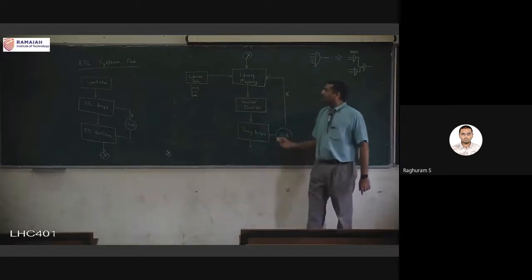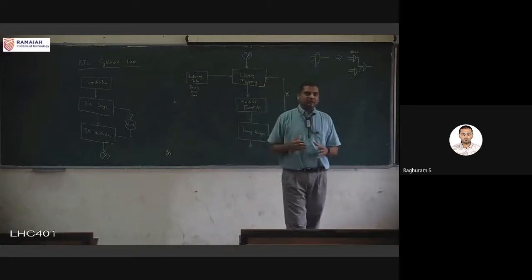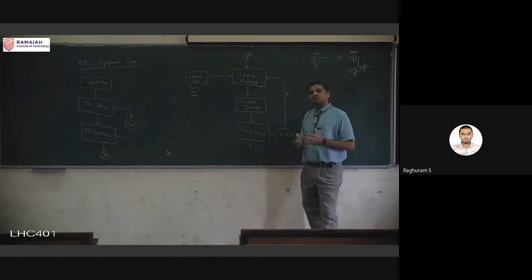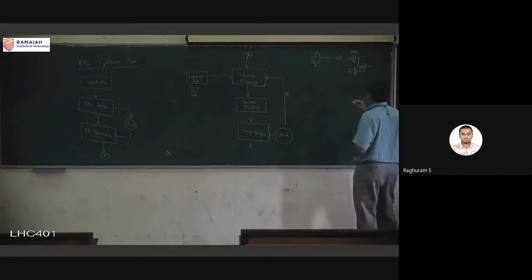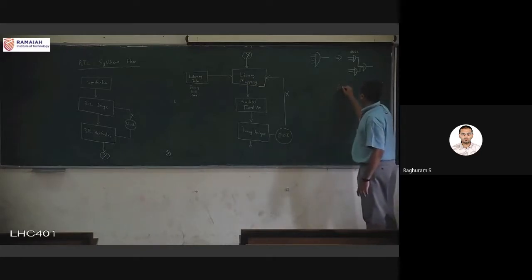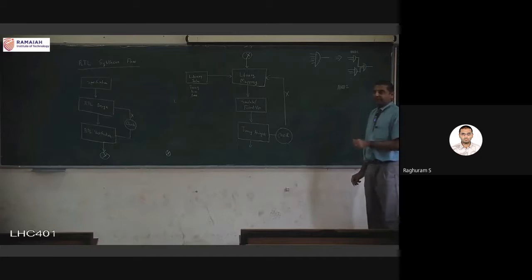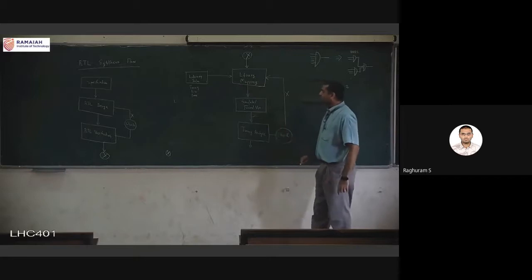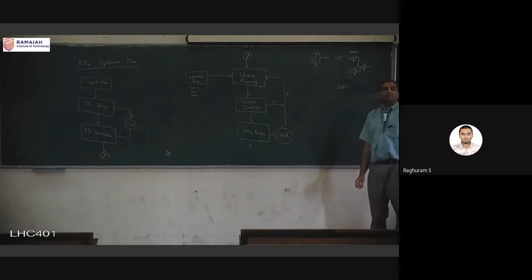What is the meaning of go back? This is the way where we are trying to maybe change the mapping. So here, for example, take this example itself, AND2 is one cell that is there in the library. We have used this in our mapping, and unfortunately the simulator is okay, formal verification also okay, but the timing analysis is giving me a problem.